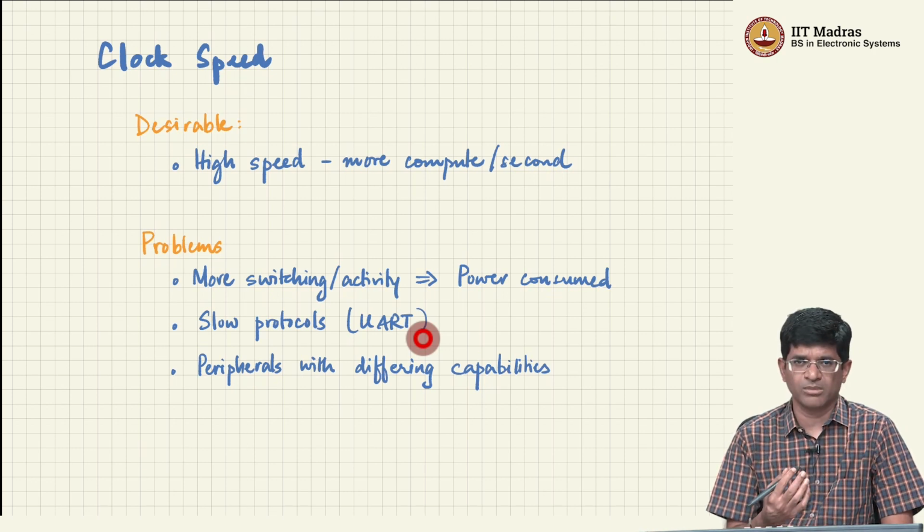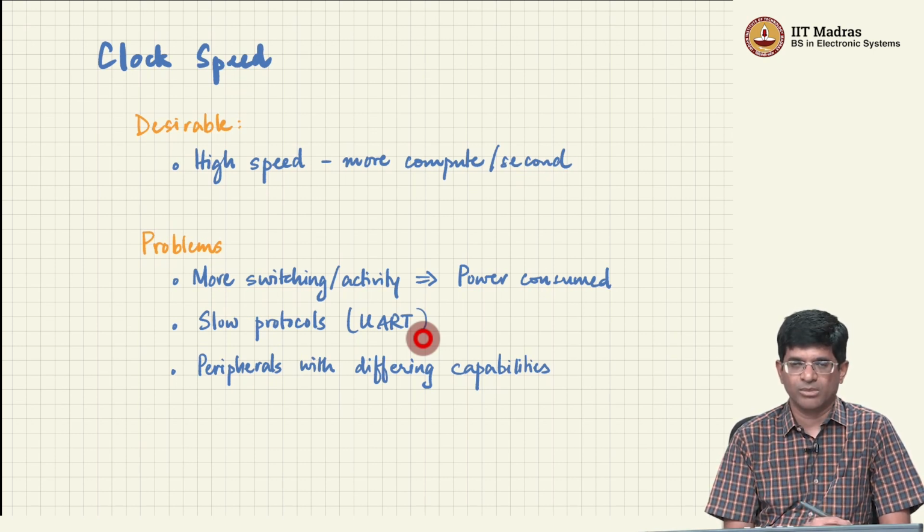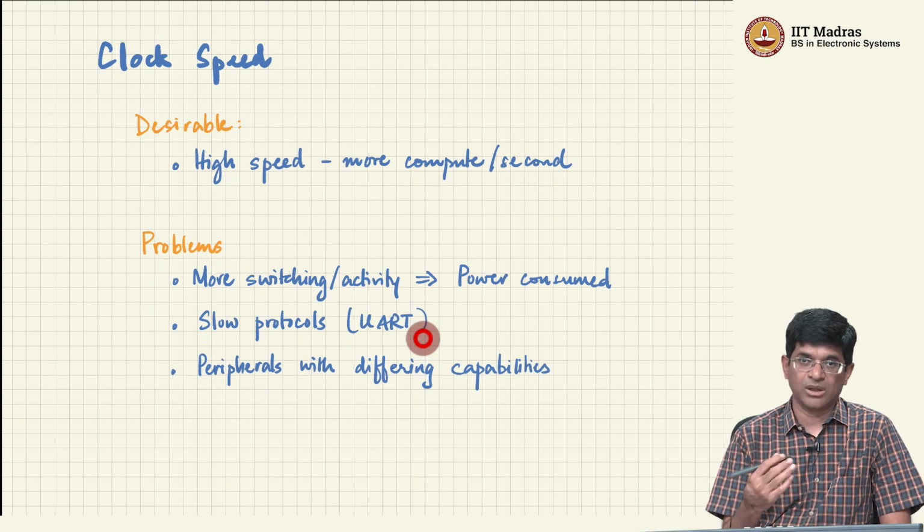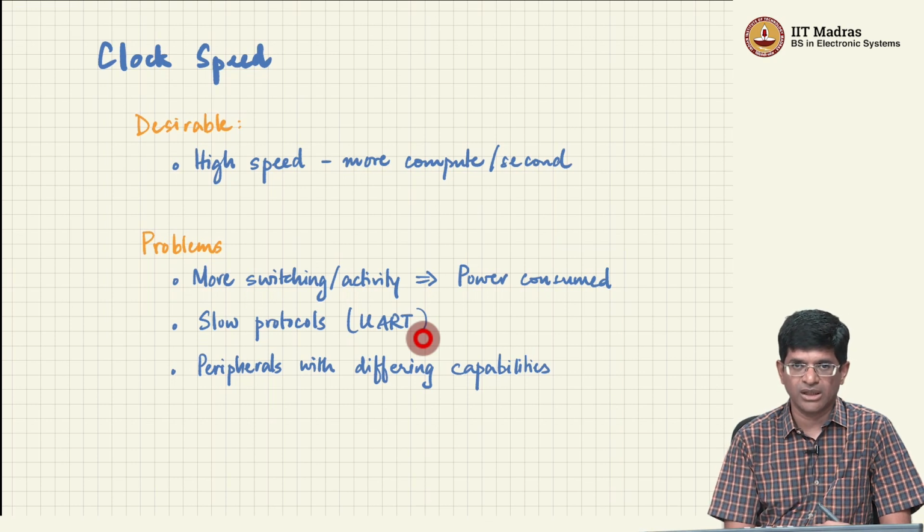It could go up more, but maybe up to around 100 kilobits per second. It's not really designed for much higher speeds than that. But the CPUs typically start at 1 megahertz and then start going up from there. So they're at least like 10 times faster than what the UART can do. So that becomes a question, right? How do I sort of balance these different clocks?